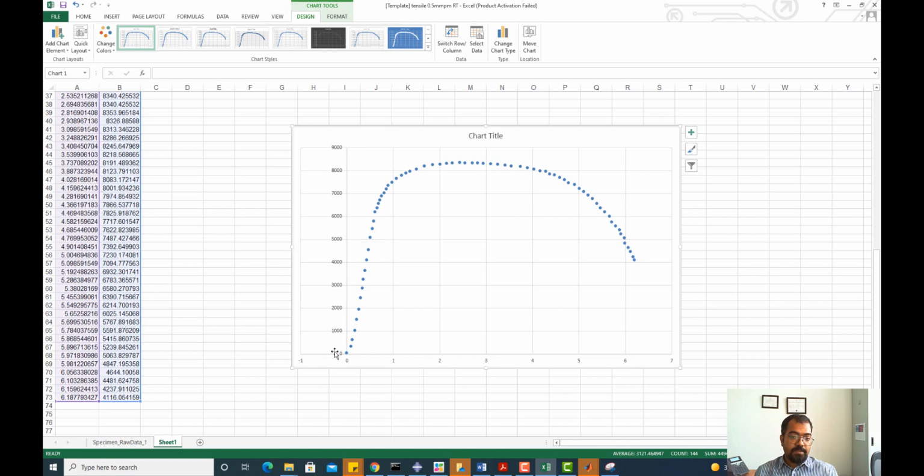Okay. So the problem is there is, in this strain, a contribution which is coming because of the machine itself, because the machine is applying load on the specimen. Sorry, I do not know if I was audible so far. So the machine is applying load on the specimen, and because of that load, the machine itself is getting elongated, right? How much the machine is getting elongated can be calculated using machine compliance. So that part we will do.